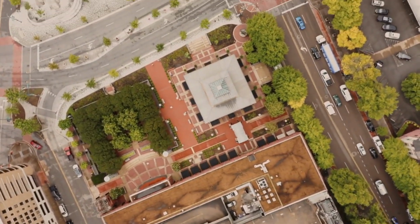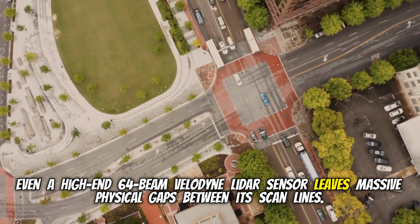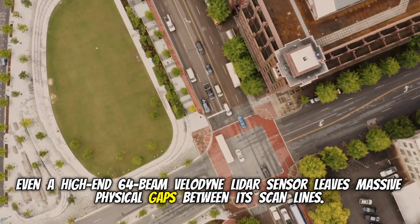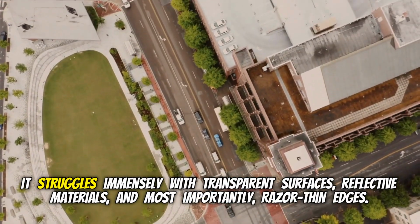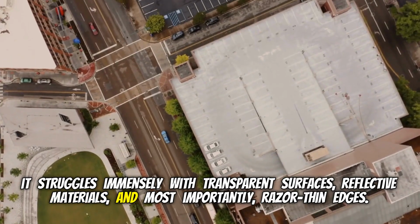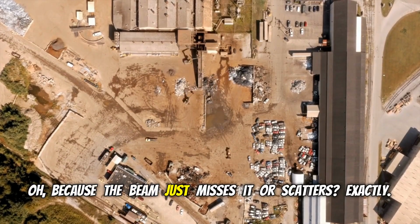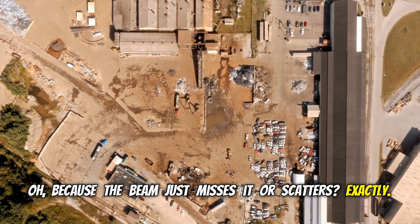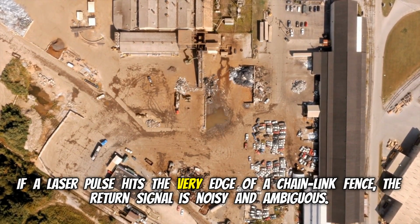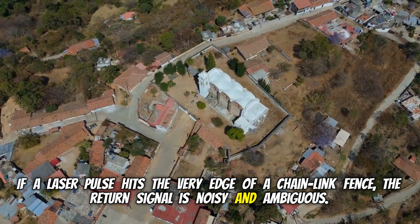Oh, really? Yeah. Even a high-end 64-beam Velodyne LiDAR sensor leaves massive physical gaps between its scan lines. It struggles immensely with transparent surfaces, reflective materials, and most importantly, razor-thin edges. Oh, because the beam just misses it or scatters? Exactly. If a laser pulse hits the very edge of a chain-link fence, the return signal is noisy and ambiguous.